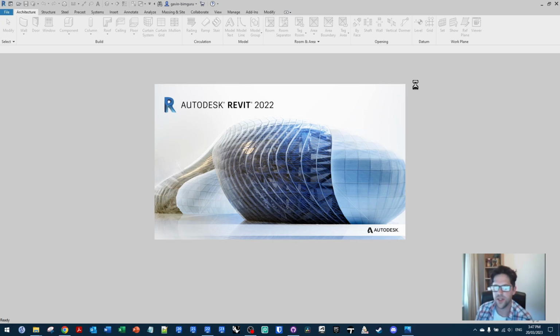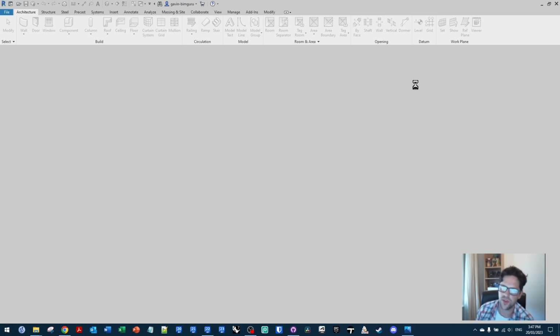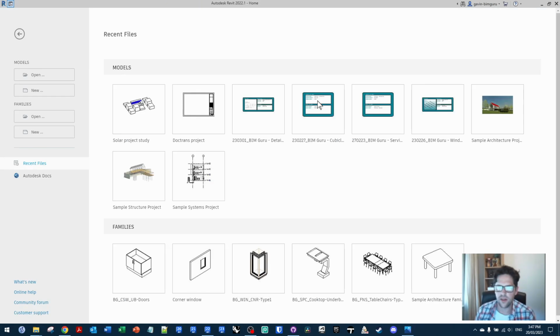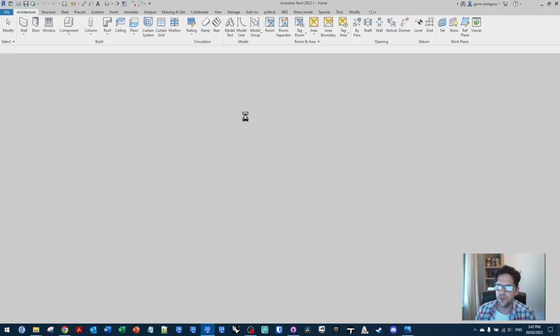I could probably actually take one test point and then visualize each vector from that point instead, just to show a sun path related to that point. So I'll just have to make sure I open up a backup of my script in this case to get the latest before I connected that automatic step. So solar project study, and we'll go back to Dynamo.